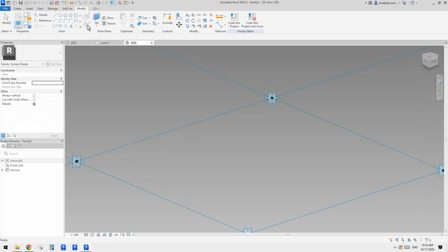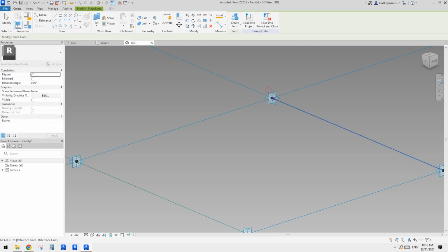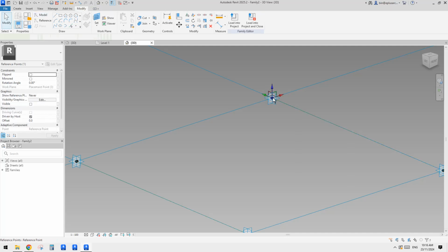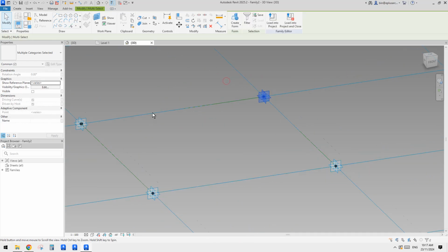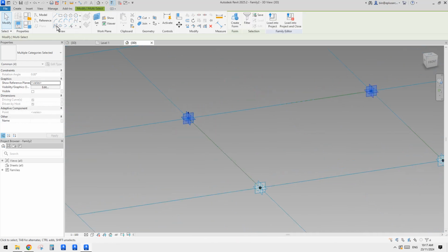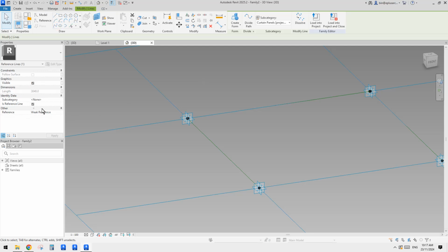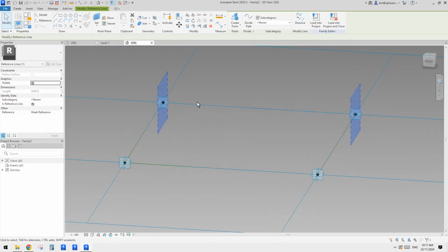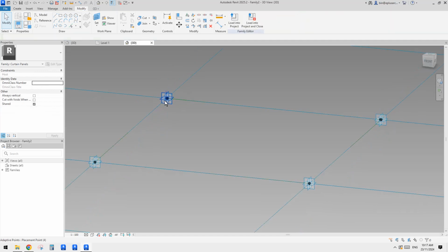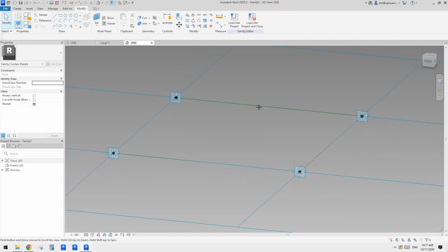Okay, so another one, draw on world plane and place on that one. Okay, select, drag. This time it will be negative, so let's do negative 10. So now we're going to select these 1, 2, 3, 4, create a spline through points, make it a reference line. Although this one still looks like a straight line, eventually it will be different. It will be a curved line.